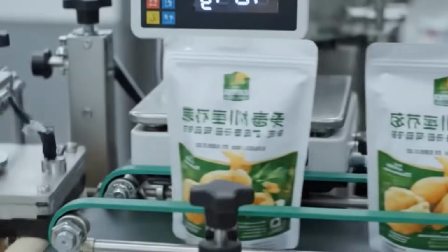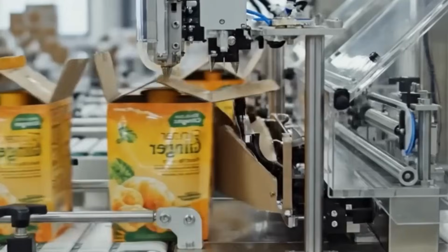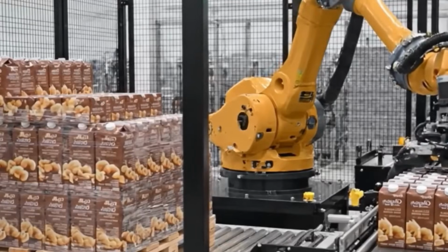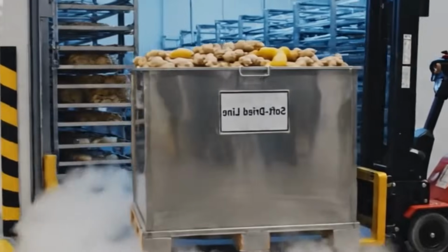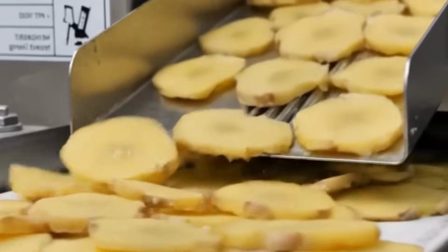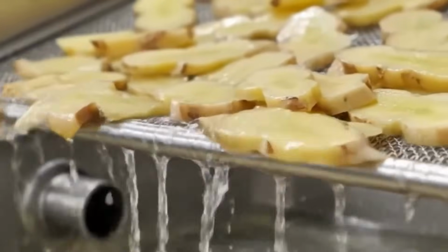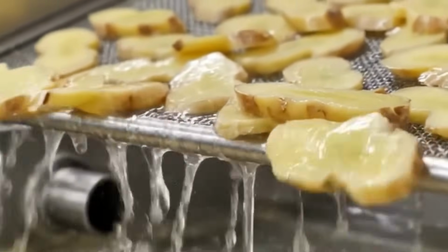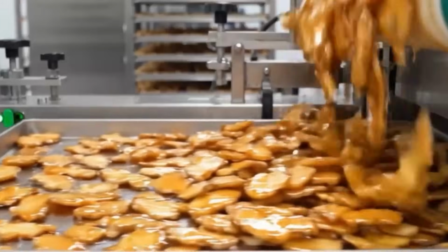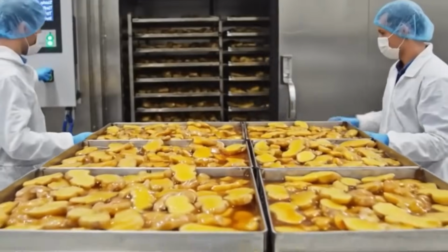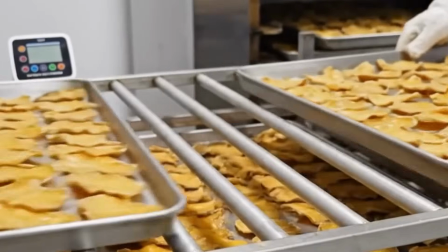Labeling systems vary by format. PET bottles pass through wraparound labelers that apply pressure-sensitive or roll-fed film labels. Servo motors control label placement, while rubber rollers press labels onto the surface. Cans use shrink sleeve applicators, where sleeves are dropped over the container body and pass through a heat tunnel. The tunnel uses either infrared or steam heat to contract the film evenly around the can. Label inspection units verify barcode readability, positioning, and design accuracy.